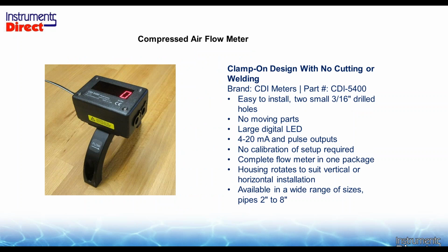And some of the tools that you're using in the waste treatment plant, you begin to monitor for energy efficiencies, your compressed air. And there's digester gas. This particular device here is for clean applications. So it basically has 2 holes you drill into the pipe, strap the sensor on, and using a thermal method will monitor flow.